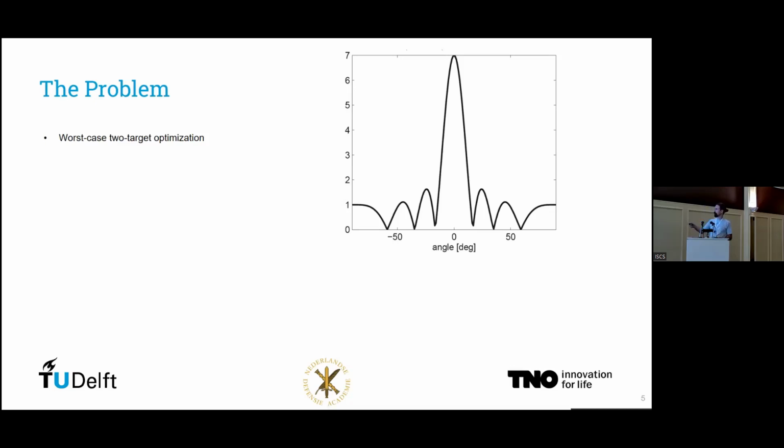So all these little lobes that you see besides the main lobe in the middle would be considered side lobes. And these are a measure of, at least the biggest one you could say is like the worst thing that one target's response can induce on another target's response. So peak side lobe level is equivalent to saying it's a worst case two-target interference.